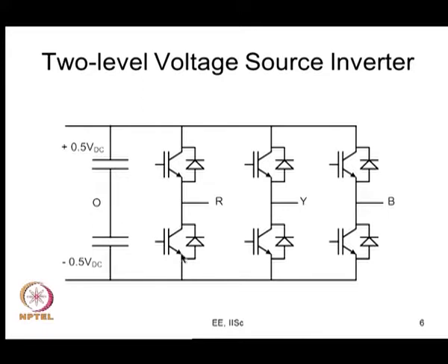This is where there is a very significant difference between the previous modules and now. The signals of the complementary switches are not exactly complementary now. But the current continues to conduct. Normally you would expect a transition from this transistor to this diode and back from here, etc. The instant at which you would expect this transition will now slightly change, as we have seen in the previous lecture.